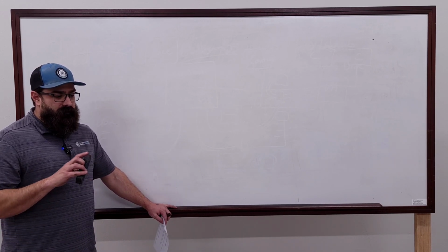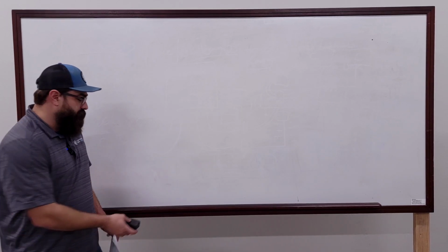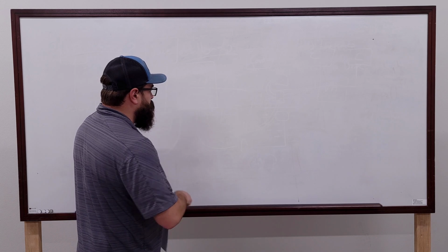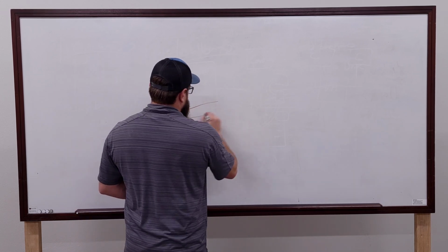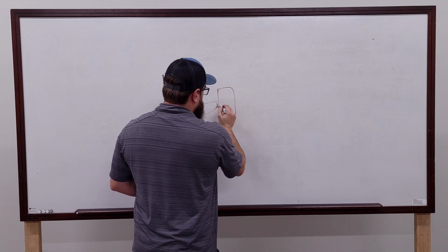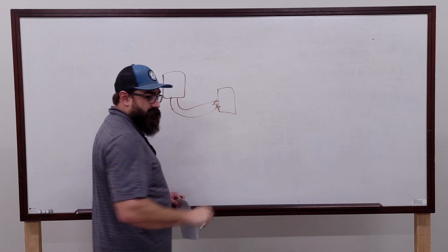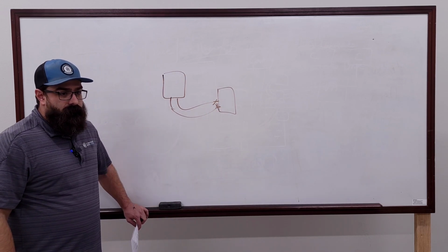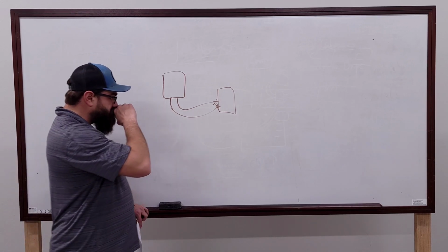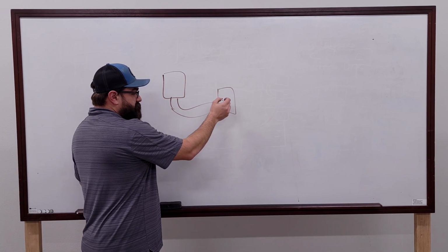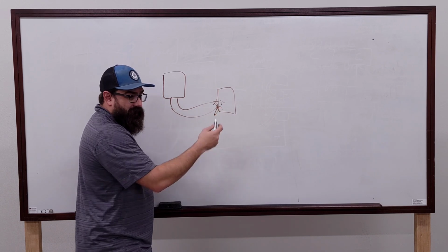But did you check for voltage at the field device? Like, so if the controller is wired up to, 2 wires come out and they go over to the SCR, did you take these 2 off and test across them to see if you had anything? No, I tested across the post where it landed, on the board. See, I would take them off because this may be screwed up somewhere or something, and it may be grounding out like I had the other night.